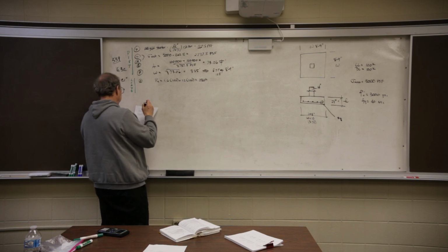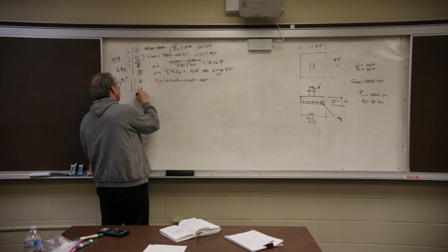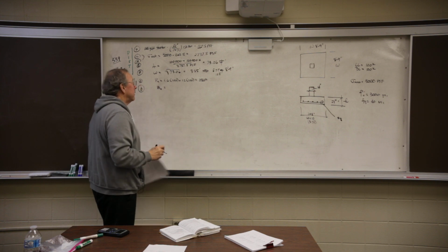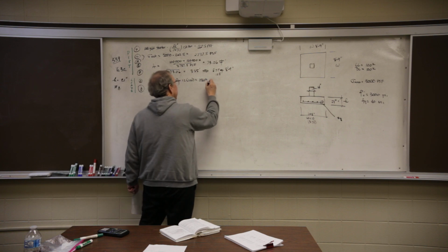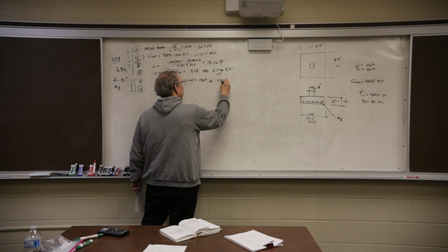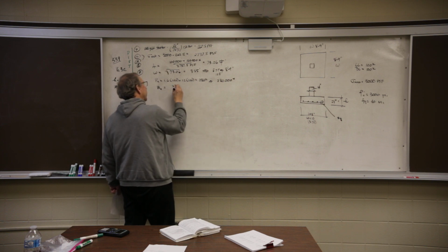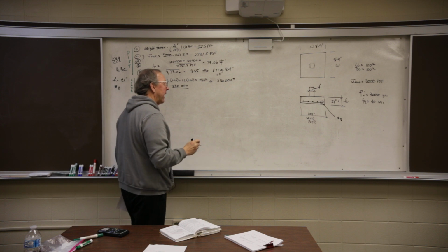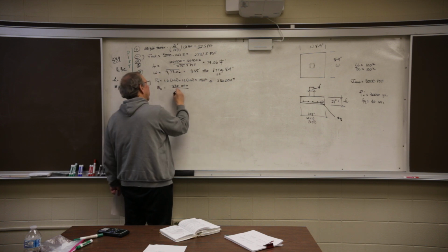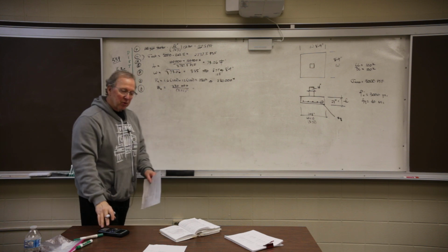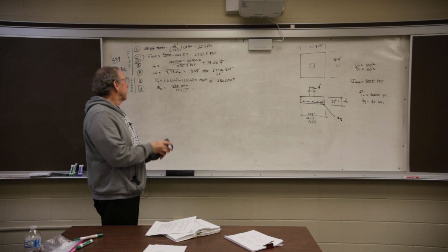So I'm going to go to J. This is the same as that PD on the last one. So I'm going to take this kips and I'm going to change it to 280,000 pounds. So 280,000 divided by the area, 8.75 squared. Squared, W times W, that's the area that's laying against the ground.